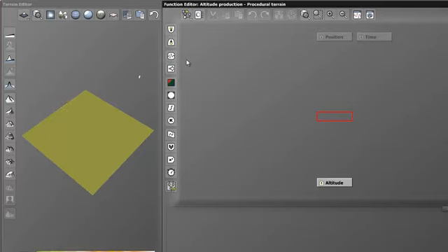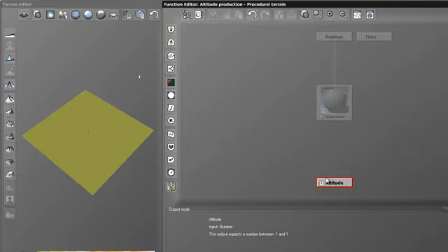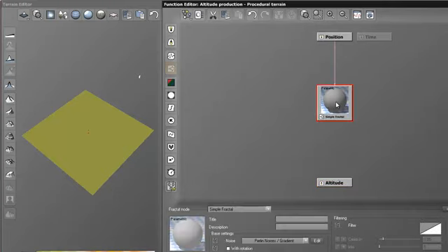Let's take an example. I just click on add fractal node, and here it will add a node, and what we're going to modify is the altitude. So what I'm going to do is take this arrow here and connect it with the simple fractal node here, and it will pop up a little dialog box where we have to choose between rough areas or altitude. What we want to modify is especially the altitude. Okay, so I'm going to click it,